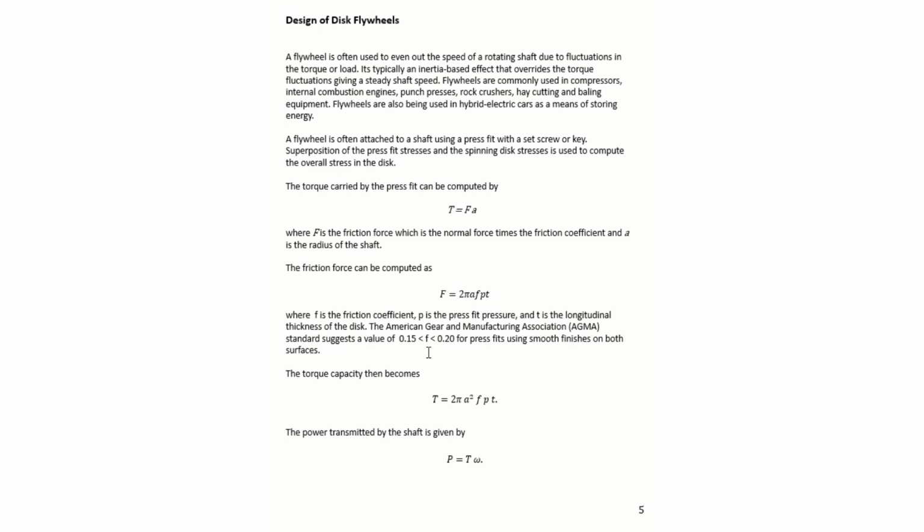Typically, a standard that is followed is a friction coefficient of 0.15 to 0.2 for smooth finishes, and this is published by the American Gear Manufacturers Association, AGMA.